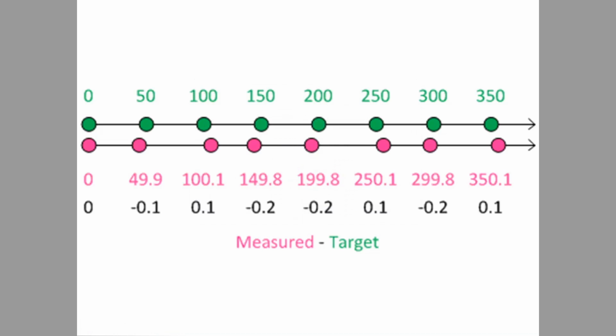The reason I like to use part programs is that it's the most universal and generic way to load comp data. Some of the newer versions of the UI have screens built in to enter comp data. Other versions have INI files that can be edited and modified. I'm not a big fan of using those because that means I have to type in numbers by hand. With part programs, I can always do some kind of copy and paste from metrology software.